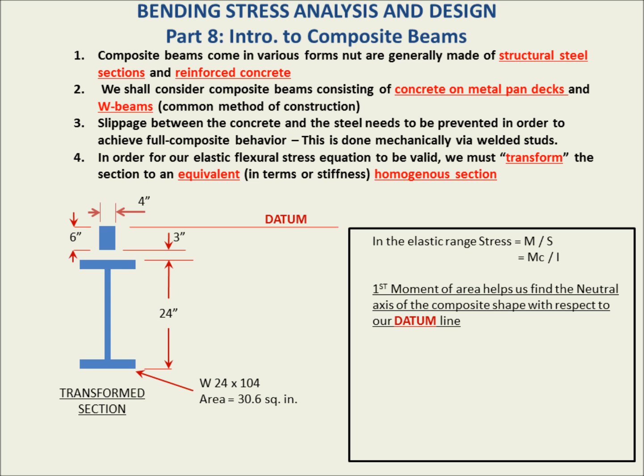The center of area also corresponds to the center of an even stress distribution. So if you have an even stress distribution over an area, the center of that area is also the center of that stress distribution. In video 2, right, where we came up with the mass moment of inertia and then related to the area moment of inertia, we saw this dance between mass and energy quantities on the one hand and spatial and geometric quantities on the other. We saw the dance from the mass moment of inertia to the area moment of inertia.